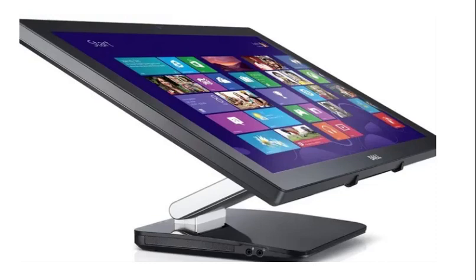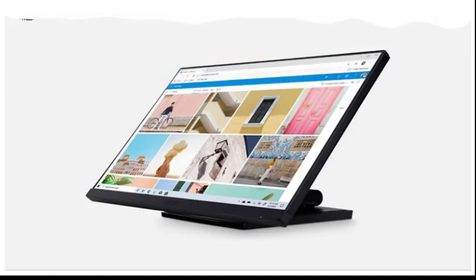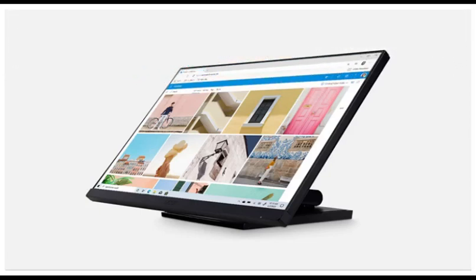Advantages. Highest image clarity and light transmission of all touch technologies. Unlimited touch life. Impervious to surface scratches. Multi-touch, 2 or more touch points. Palm rejection capability. Disadvantages. Accidental activation may occur because the infrared beams are actually above the glass surface. Dust, oil, or grease buildup on screen or frame could impede light beam, causing malfunction. Buildup of snow and pooling of water, such as rain, can cause false triggering. May be sensitive to direct high ambient light interference.